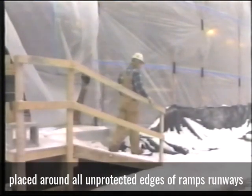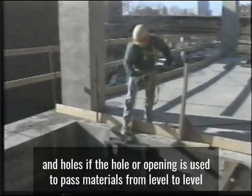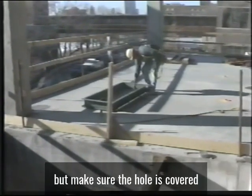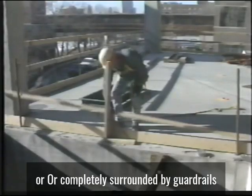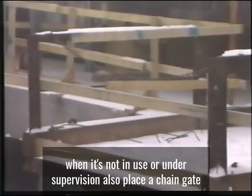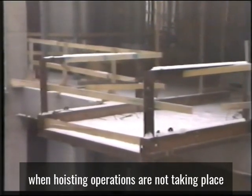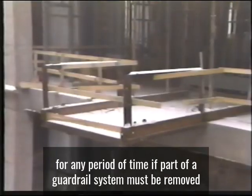Guardrails are placed around all unprotected edges of ramps, runways, and holes. If the hole or opening is used to pass materials from level to level, two sides of the guardrail can be removable sections, but make sure the hole is covered or completely surrounded by guardrails when it's not in use or under supervision. Also, place a chain, gate, or removable section across the opening of a hoist area when hoisting operations are not taking place or when the area is left unattended for any period of time.